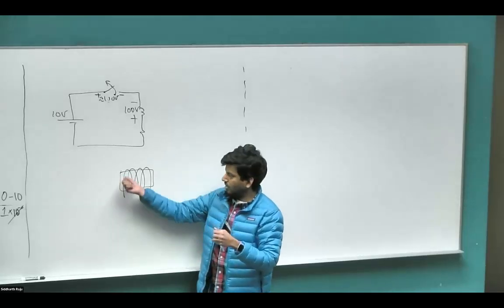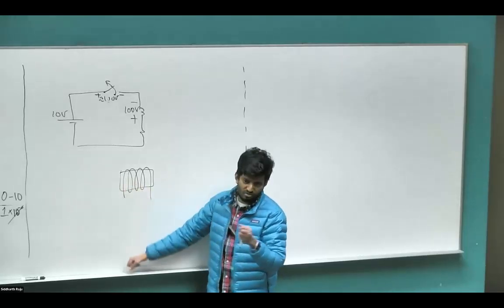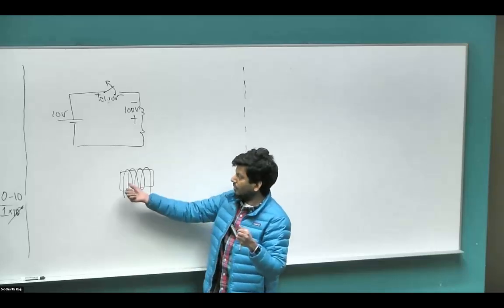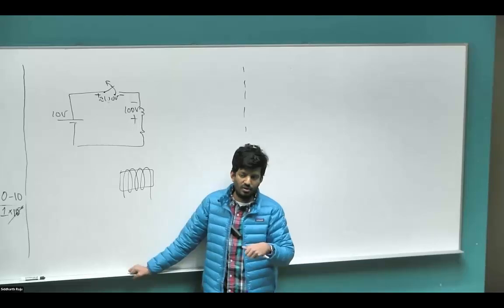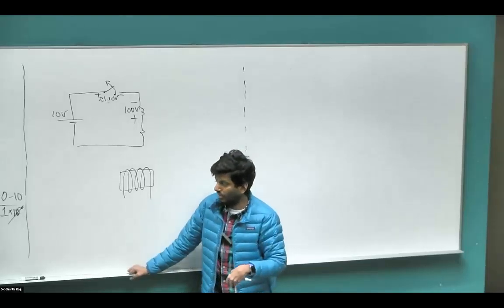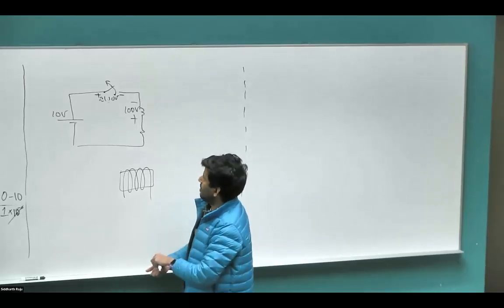And these are typically varnished so that the two turns do not short one another. If the voltage across the turns is very large, then the varnish can puncture and then a turn-to-turn short will appear in your inductor or motor or whatever it is you're trying to switch. So this is not a viable option.